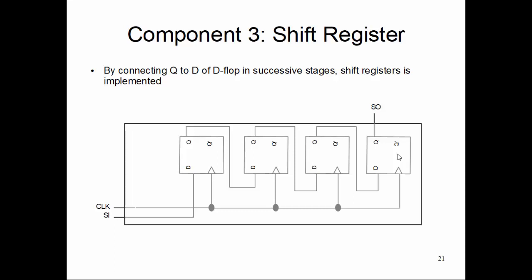So it's not really the daisy chain connection, but the concept is kind of similar, like each toggles with the clock as an input from the previous stage Q output. So it's a similar fashion. I believe the Q was connected to the clock of the next stage in those toggle registers. But here we have the clock as independent.